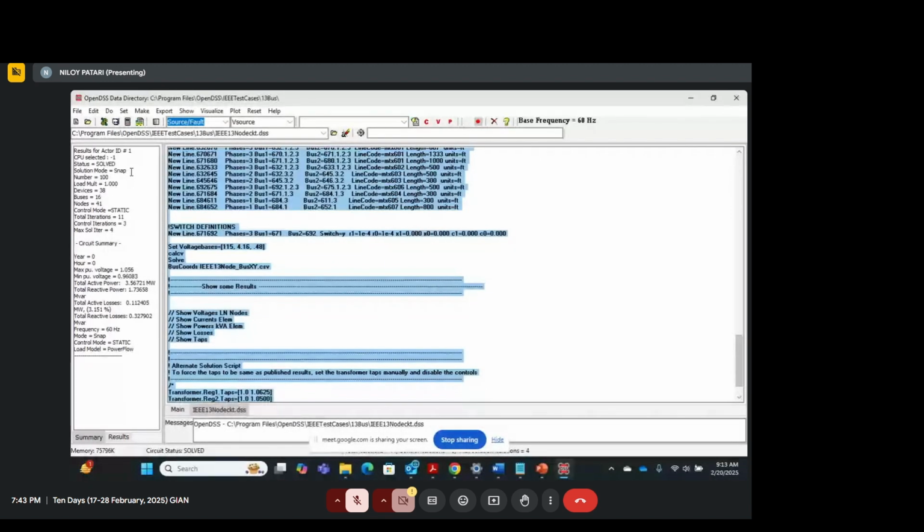What I mean by snapshot solution is that whenever we code power flow, it's a snapshot. You have defined loads, you have defined and initialized voltages and everything. When you do Newton-Raphson, it takes that particular load, takes a certain number of iterations, and solves it.